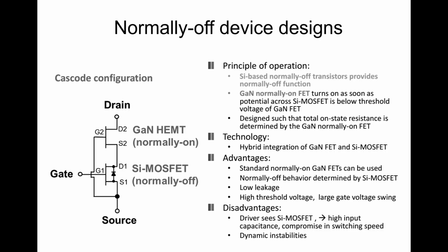So the driver sees silicon MOSFETs. So you're limiting temperature, for example. So you go back to the limitations, basically, of silicon somehow. Okay, and also in terms of instability, dynamic instabilities, this is not trivial. So that's probably the SOA is more restrictive in this case. Okay, but some people are using them.